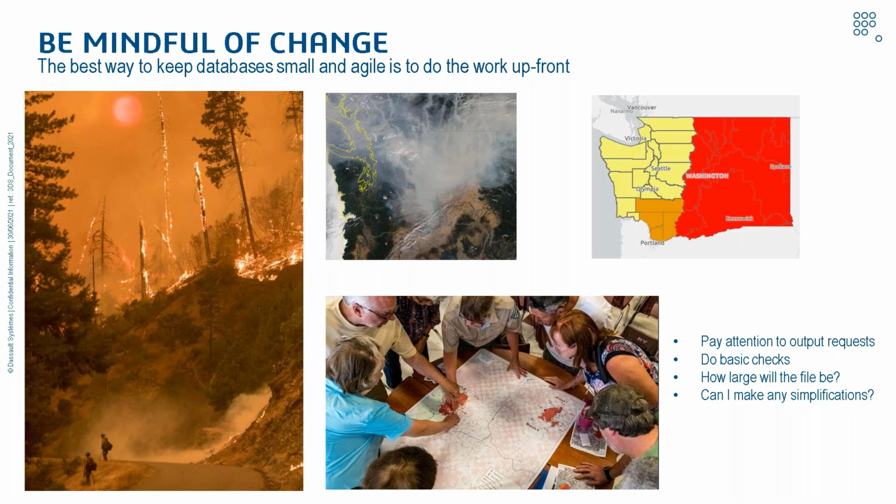If I multiply that by 3, multiply that by 1 million elements, and multiply that by the size of a floating point number, I can get the total size that output request is going to take on disk. And that's a fairly easy calculation to do. And you can make that general calculation for all of the data and get a very quick estimate of about how much data you're requesting.